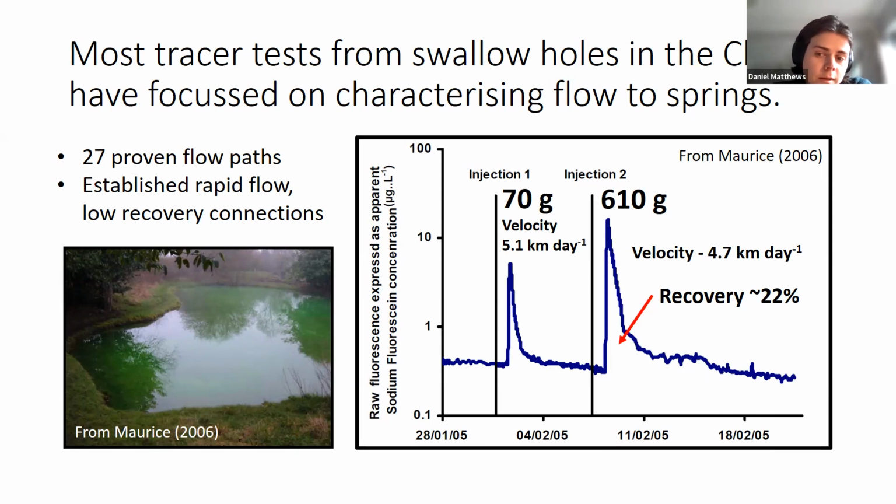And again, for the Sherwood sandstone, that was considered quite a considerable flow rate. And also another note here, compared to other chalk aquifers in Northern Europe, there's been relatively little trace testing done in the UK. You know, in the chalk aquifer in northern France, trace testing is a lot more commonplace.